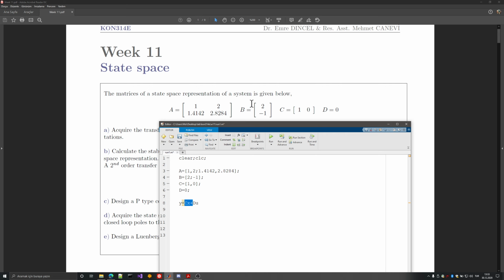And the way the inputs are affecting the system states or internals is defined by this input matrix, and then we have the autonomous matrix that defines the differential equation, and C is the relation between the states and the output. You can see from here, because the input is u and the output is y, this is a relation between u and y.